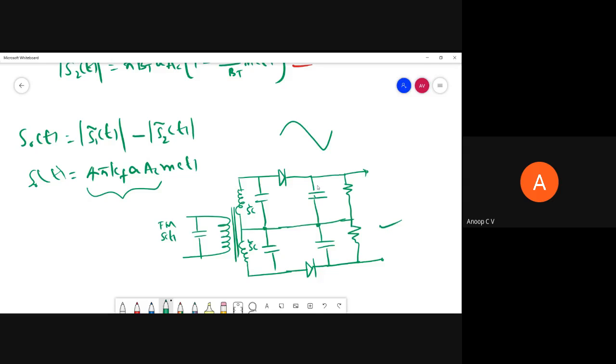The envelope detector clips off the negative part with a diode, and this low pass or smoothing filter smooths out the ripples, just like how we smoothed out the rectified output using a filter. Same thing is happening here. From the half cycles, we get the envelope back by passing through a filter. That's what is happening. So that's all about today's session.